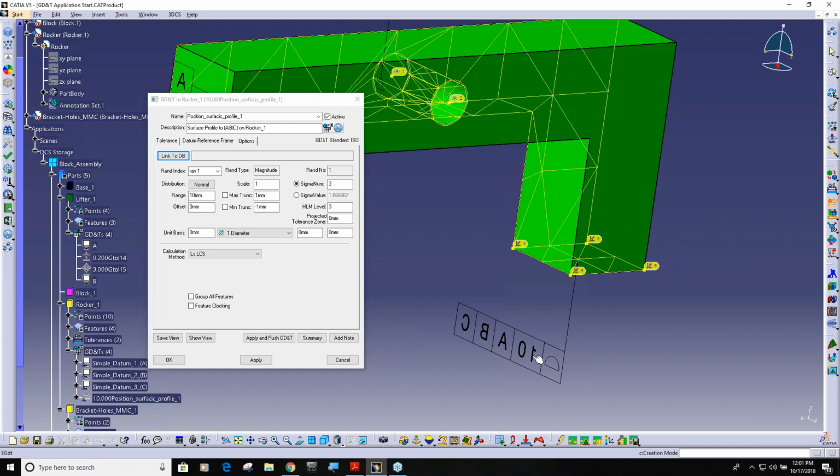Can you push it back in Creo? All three. The developers have pushed it out. The only thing that you can pull in and push back is the range, the defined offset, the projected tolerance zone, and I think the modifier. You can do that for all three platforms. Wow, guys, I'm excited. I didn't know that.